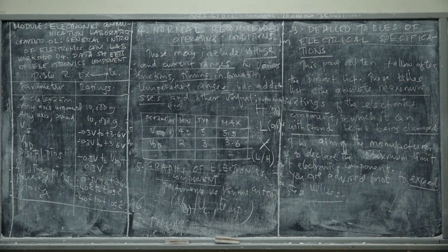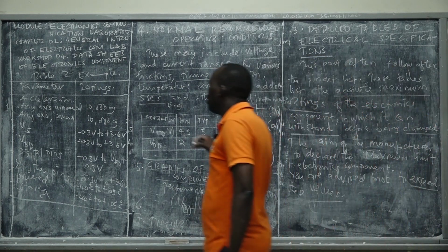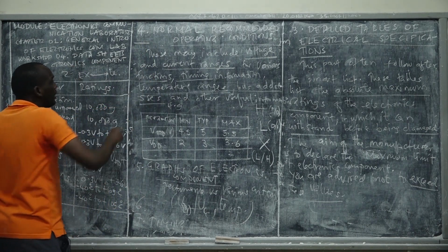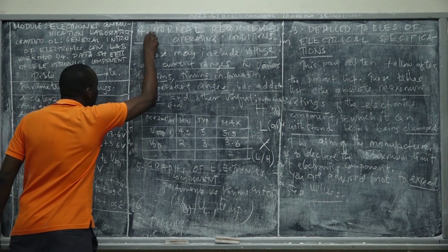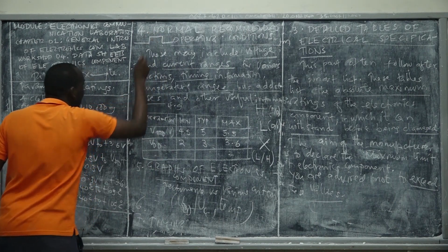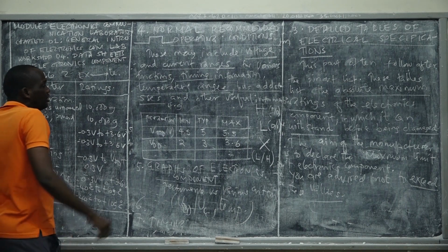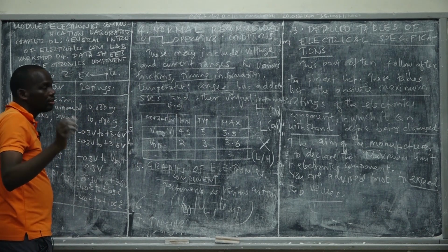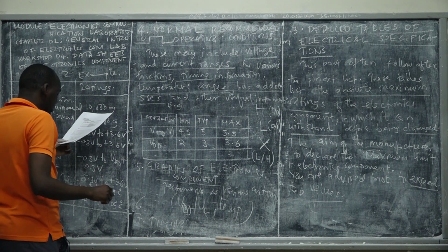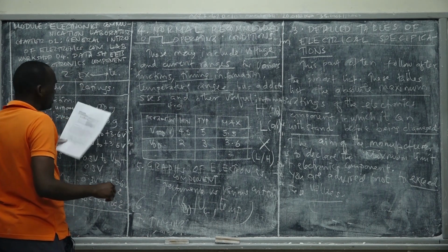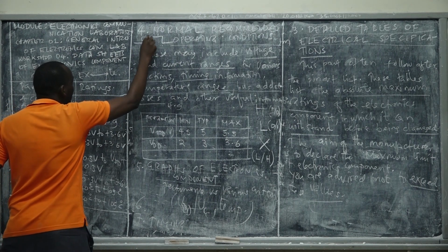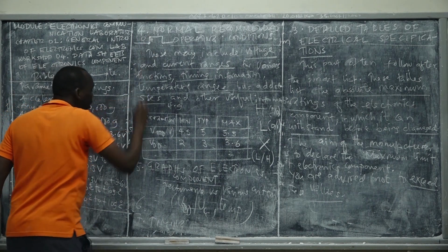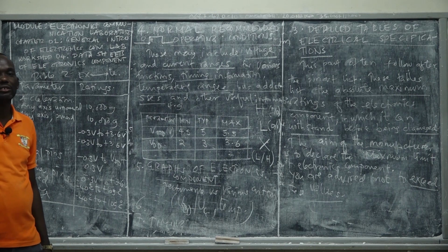Say rise and fall. When you talk about a digital signal, if you have bit number 0, this is its timing diagram. If you have bit number 1, this is its timing diagram. Stop writing, stop drawing. This is bit number 0. This is bit number 1. So listen. When the signal is rising, for instance, from here, we have a rising of the signal from this point to this point. We call this the signal rising, or rise time.